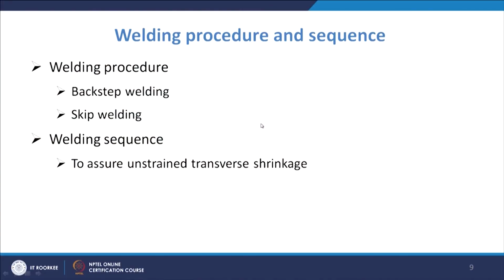For the welding sequence, you have to have a proper sequence so that the transverse shrinkage is reduced.